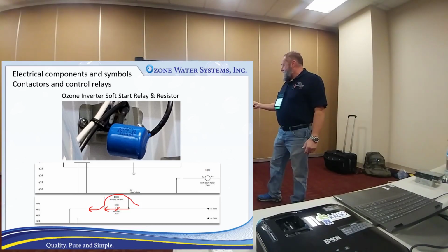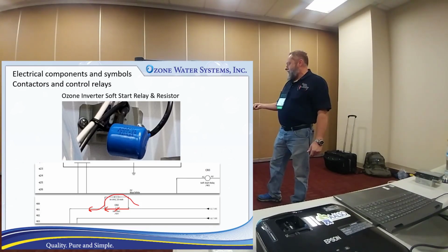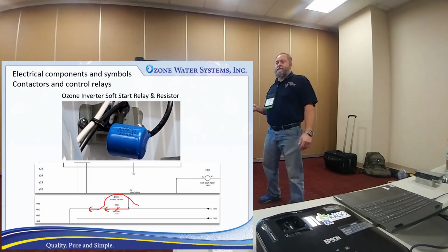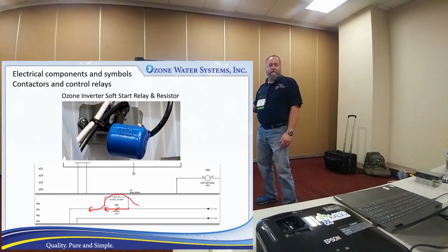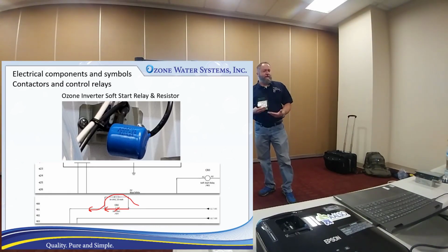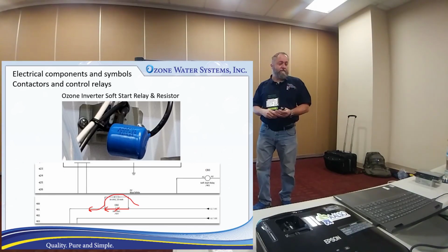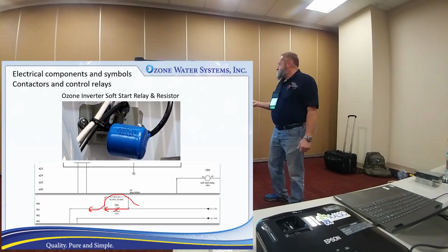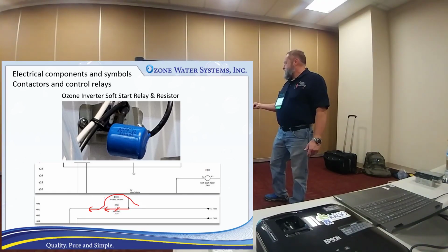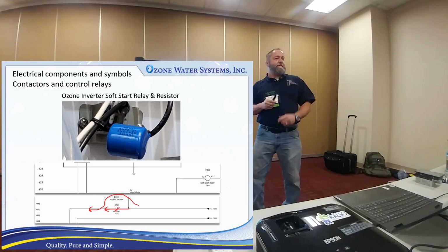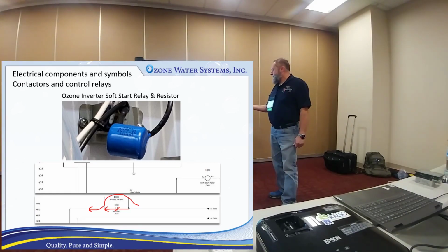If a scenario happened where that relay failed, all the power is going to try to go through that resistor until it smokes. They've actually updated the firmware on the PTI inverters to better recognize when something like that's occurring. I'm not sure how they do it or what algorithm they're using, but it does have a stop-start fault on it, and it'll tell you when that happens, when it'll shut off. If it doesn't, and that keeps running current through that little resistor, it'll just smoke. It'll turn into a little charcoal briquette. It's a little black crispy thing, so it won't work after that.